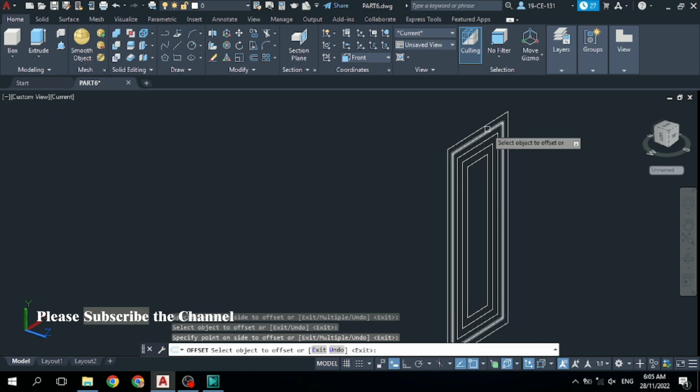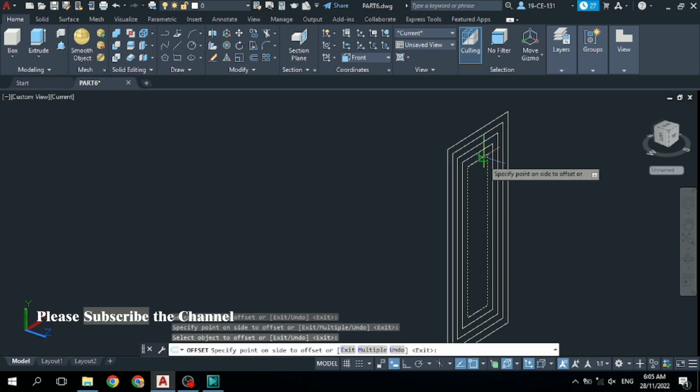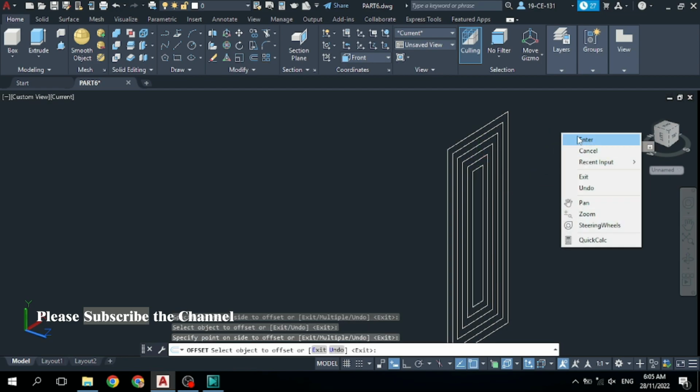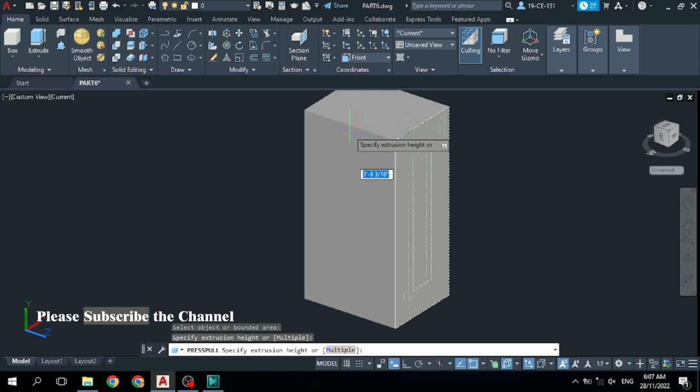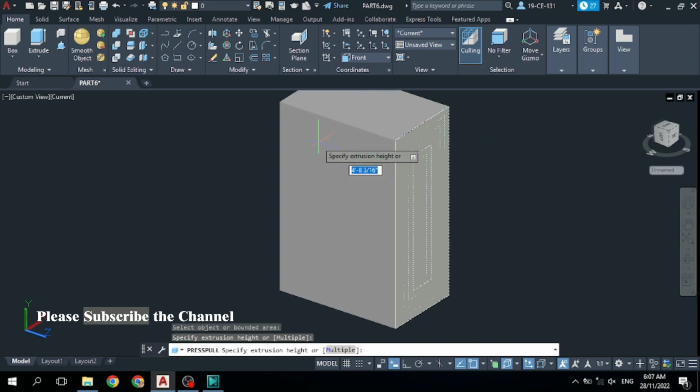Offset it 1, 2, 3, 4, 5, offset it inside 5 times. And after that, click on this press pull command. You can see this press pull and select this outside rectangle and go to the back side and type 4 inches distance and press enter.